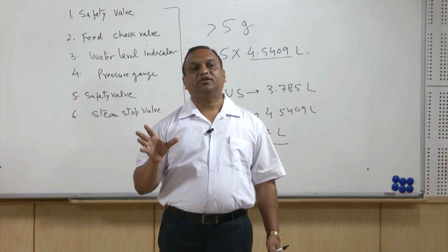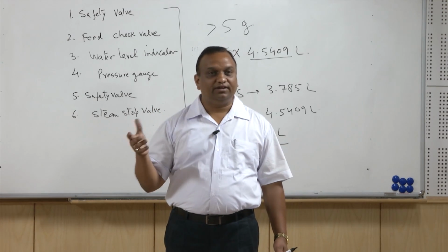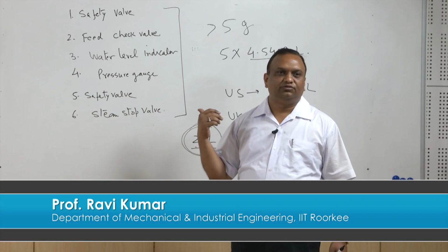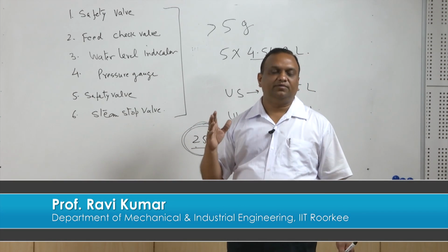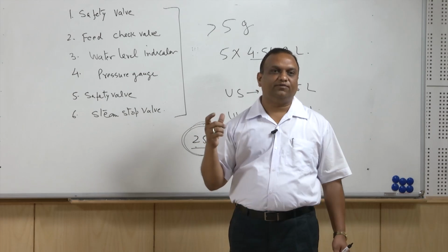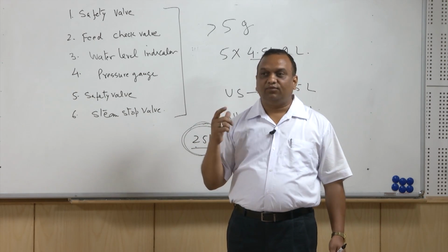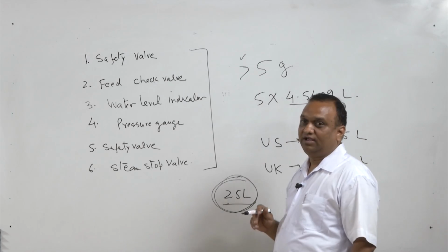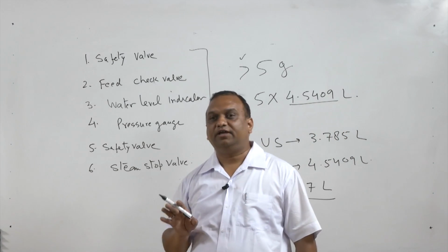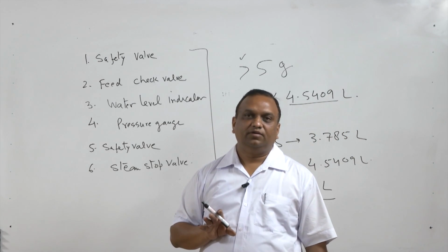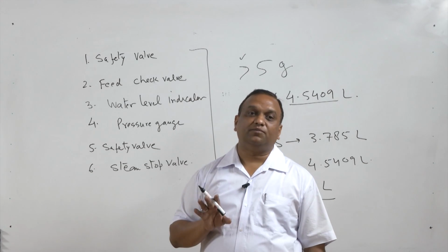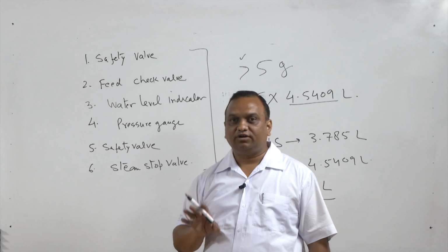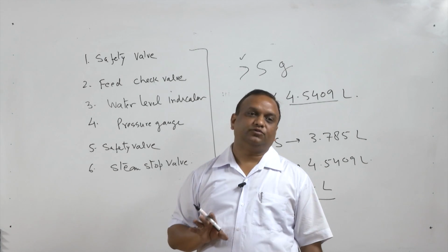For steam supply, suppose there is a pipeline for supplying steam. If the diameter of the pipeline is more than 10 inches, it is again subject to inspection under IBR. It is a very thick, very large document, and one has to be thorough before operating any boiler, because boilers are covered under IBR, and IBR was formed in 1925 because during that time there were a number of accidents in boilers due to improper upkeep of the boilers.